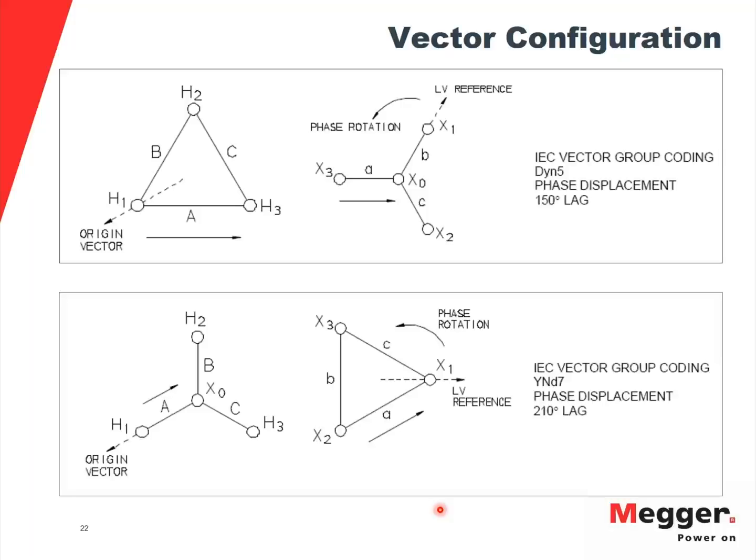So kind of going back to Dinesh's point about the DLRO and everything, this is once again a safety issue here. And of course, if you had an open circuit during normal transformer operation, it'd be detrimental to the transformer and the tap changer there.